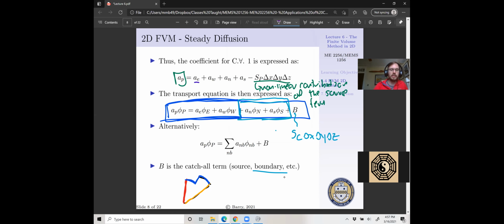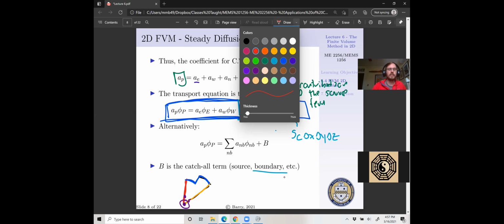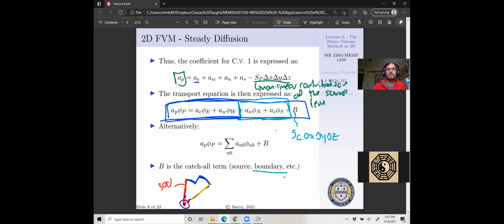And what you notice is when you do the finite difference method, you have one node down here at this bottom location. That node can't take two temperatures simultaneously, right? This might be 300 Kelvin, this might be 200 Kelvin. And that node, you go, well, what's my temperature going to be? You can't average them because that changes the solution. You can't alternate between which value it is depending upon what you're solving because you're never going to get convergence.